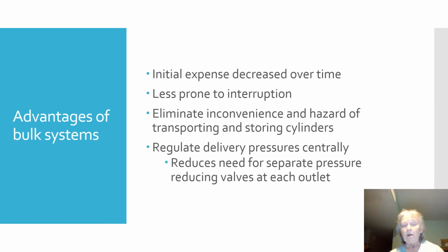So why do we have a bulk system? Well, first of all, you don't need as much storage area, and that's really important. There are certain requirements about where you can store cylinders, and you can have them, but somewhere around 5 feet away from sidewalks, 10 feet away from churches and schools, different things like that. So, depending where your hospital is, you'd have to be in the middle of a baseball or football field if you're going to try to do cylinders for the most part.